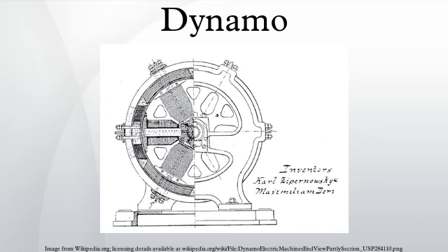The dynamo electric machine employed self-powering electromagnetic field coils rather than permanent magnets to create the stator field. Wheatstone's design was similar to Siemens', with the difference that in the Siemens design the stator electromagnets were in series with the rotor, but in Wheatstone's design they were in parallel. The use of electromagnets rather than permanent magnets greatly increased the power output of a dynamo and enabled high-power generation for the first time. This invention led directly to the first major industrial uses of electricity.